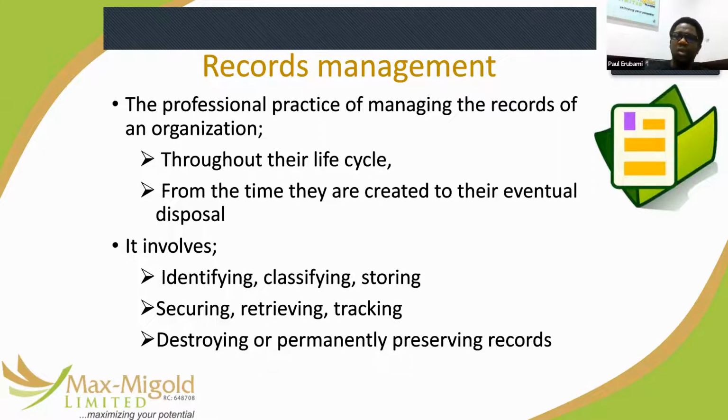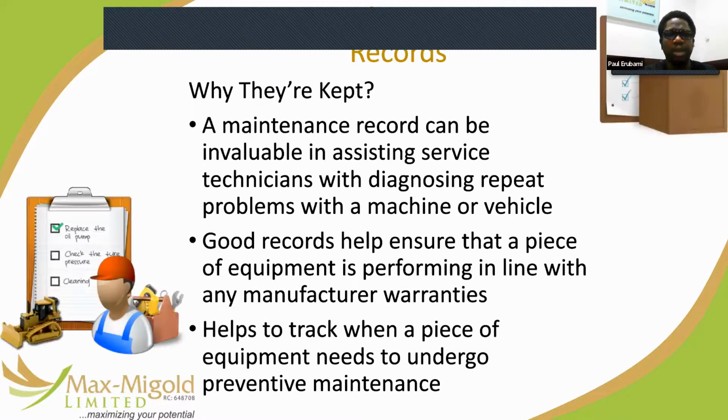But it's important that you have the records for people to be able to assess at some point. If you have a chiller system that has been here for 25 years, you cannot lose information on how many times the compressors have been replaced, you cannot lose how many times it has failed. That reporting that is extracted from the work order must be kept perpetually on site or in a retrieval system so that people can get access to them.